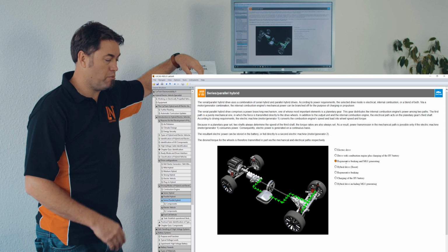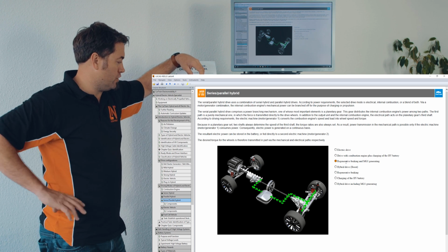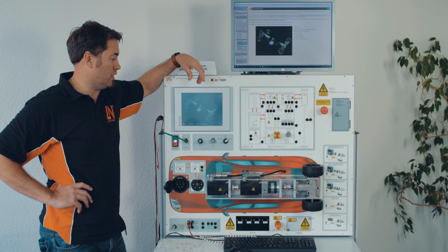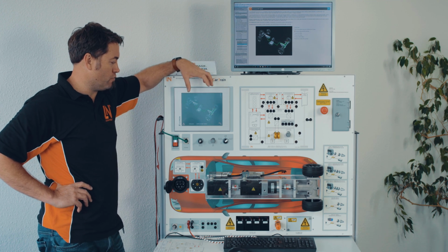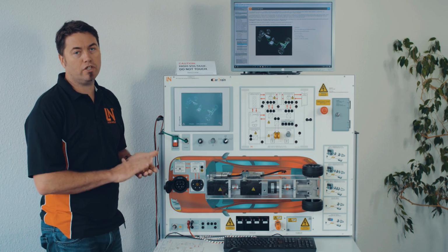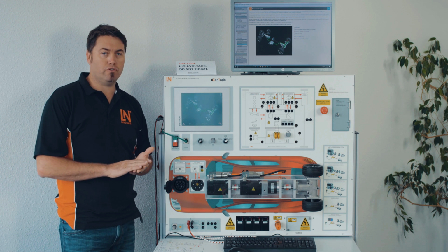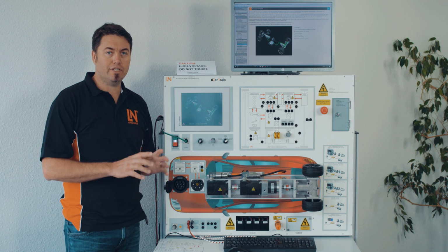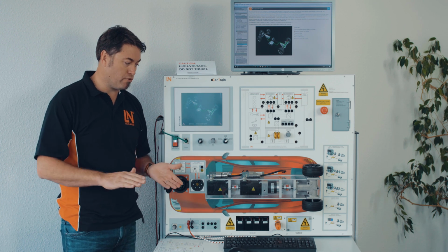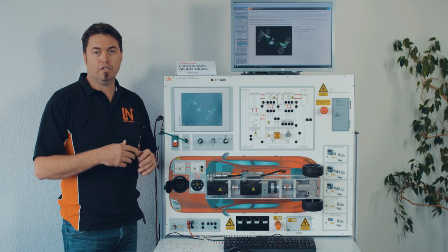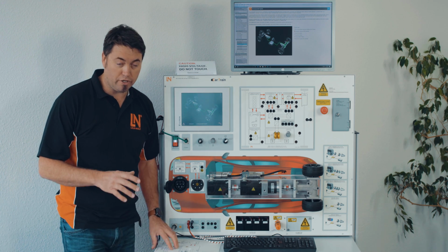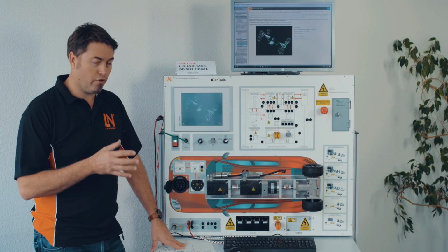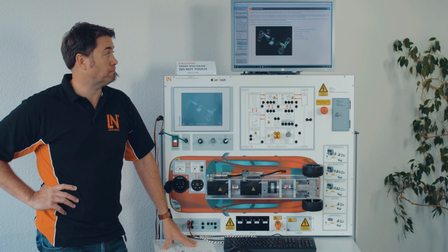Now, of course, every manufacturer is slightly trying to change the way they do it, trying to outsmart patents, that type of thing. But this is the general idea. The technology behind these vehicles is basically the same. The way a motor is driven is the same for an electric vehicle as it is for a hybrid vehicle. The high voltage battery is there, the inverter needs to be there, the type of motor is also there. Even if it's an induction motor or a permanent magnet motor, the inverter still basically works the same way.